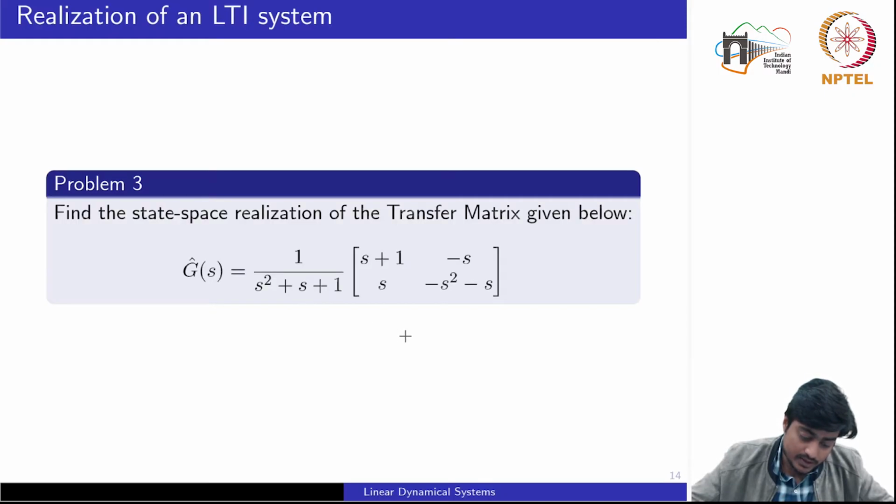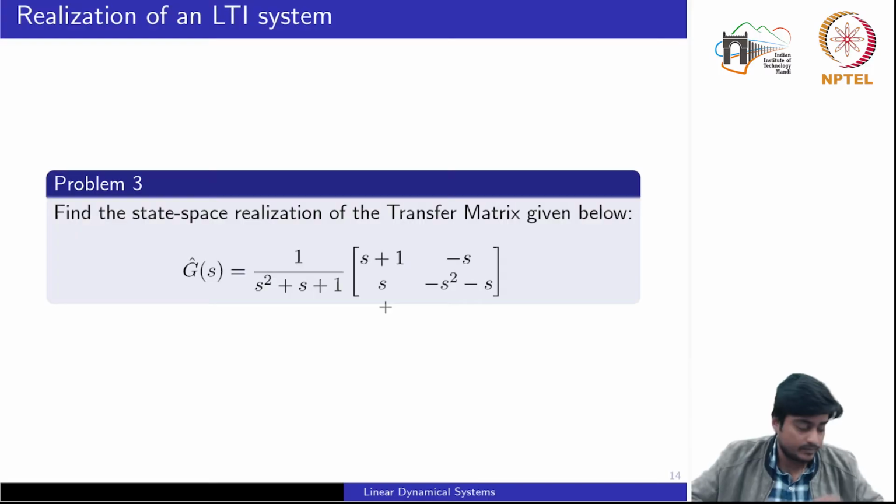So if you recall the theoretical results, we have supplied the conditions under which we can say a transfer function or a transfer function matrix is realizable. And particularly for the LTI system, we have used a specific representation, which we have also called the canonical representation, and that canonical representation was nothing but the canonical controllable representation. So we'll see how you can obtain that specific representation, but at the same time we should not forget that the transfer function is a unique representation, but the state space representation is not unique. So we will obtain one specific representation. Otherwise there exist an infinite number of representations.